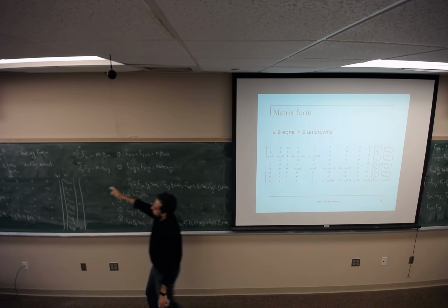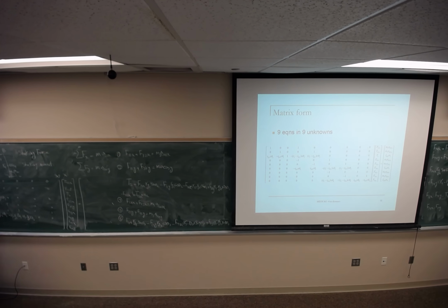We have 2 forces applied to the ground: one from link 2 applied to the ground, where ground is 1, plus, because we have two joints connecting to the ground, the force coming from link 4 applied to the ground. The summation of these two is called shaking force.